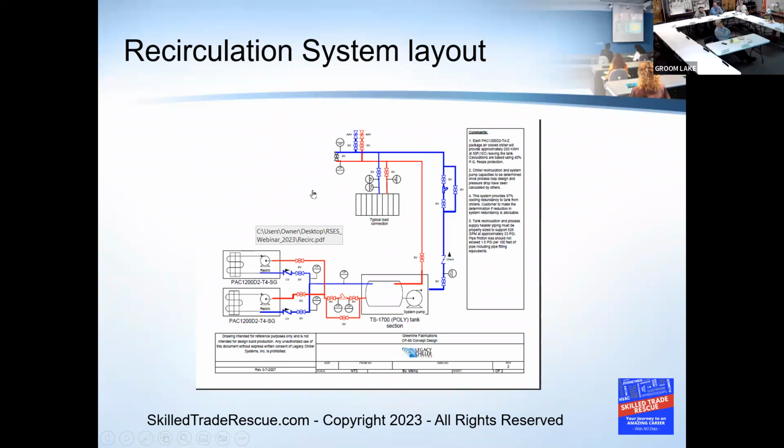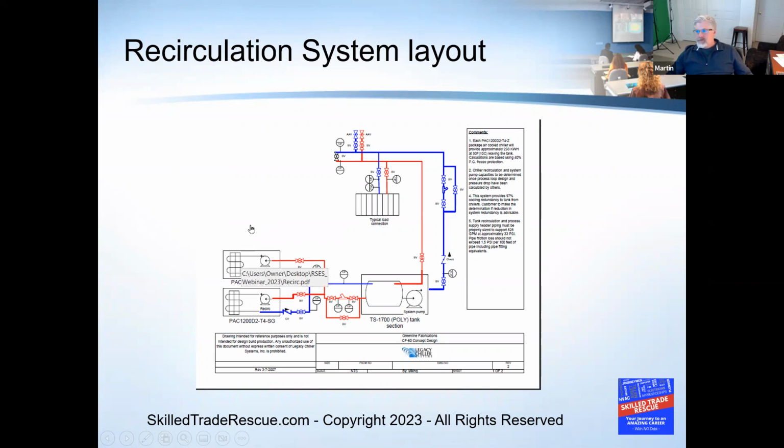So in this example, you've got 2 chillers, but you could have 3 or 4, or maybe the first couple stages could have unloading in the chiller itself too. Exactly. Yep. Turn down ratio. Yeah, that's exactly right. And what it does is it gives you the ability. So in my example here, we got 60 degrees coming in here.